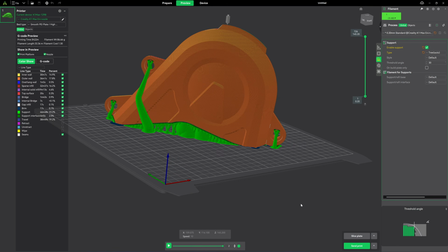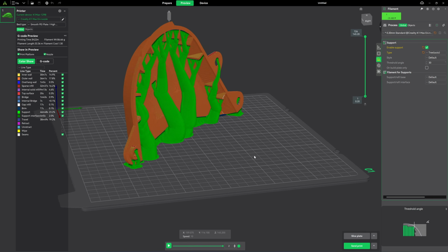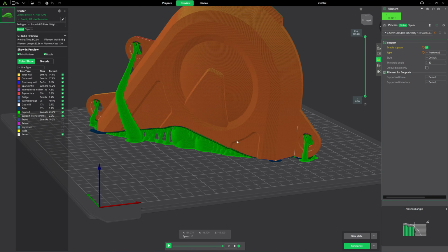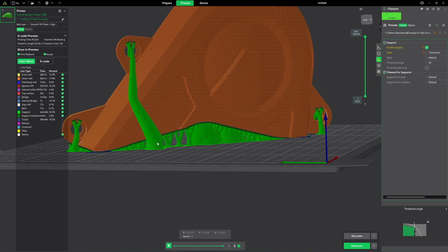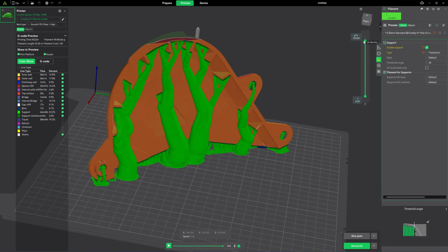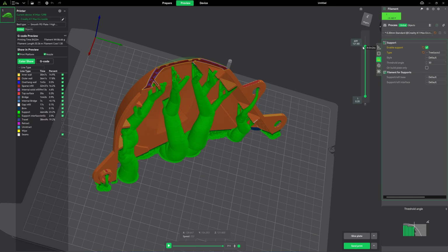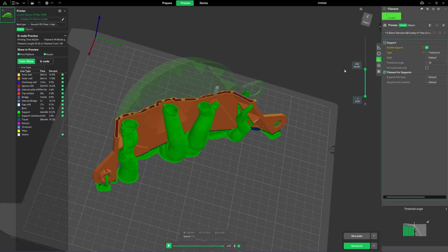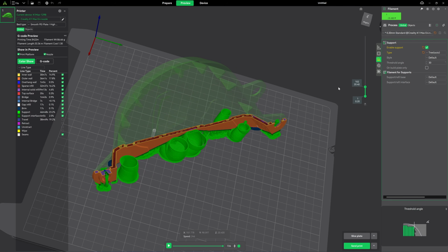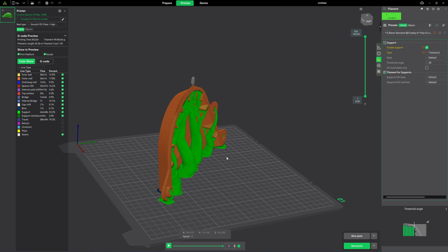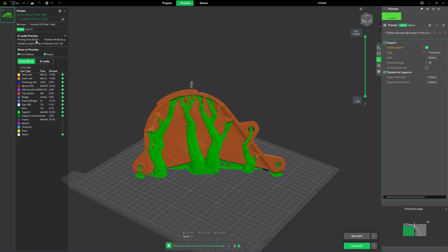Okay, now it's not clashing. Very exciting. Many times it will clash while I do slicing. So there will be support on the edge here, and the surface will be rough. Okay, let's send it for printing. 3 hours and 22 minutes. 86 grams of filament.